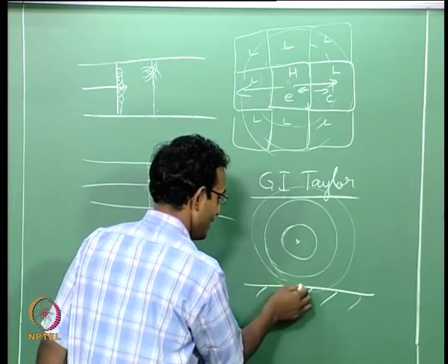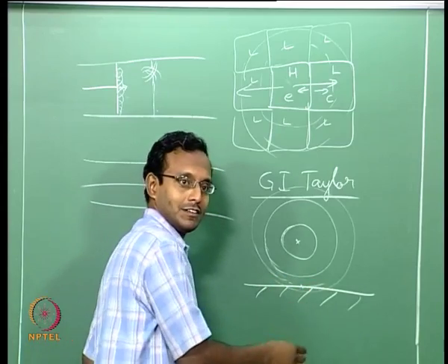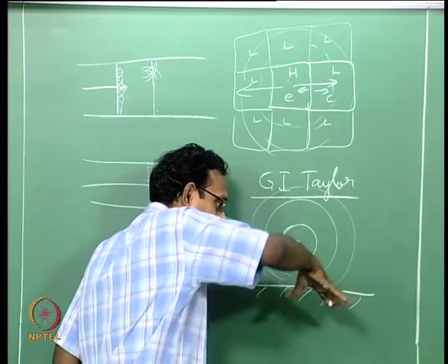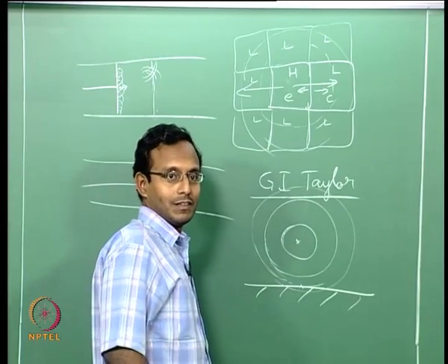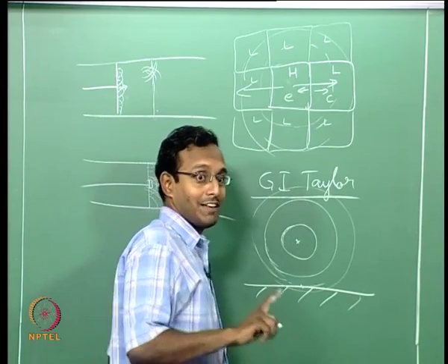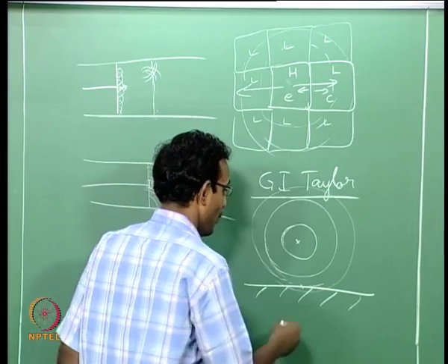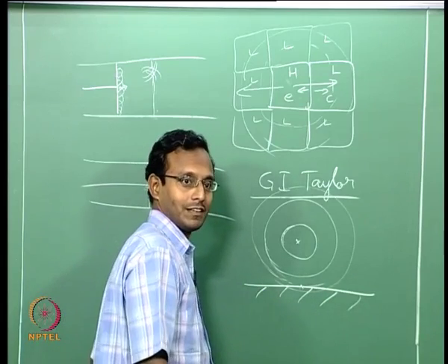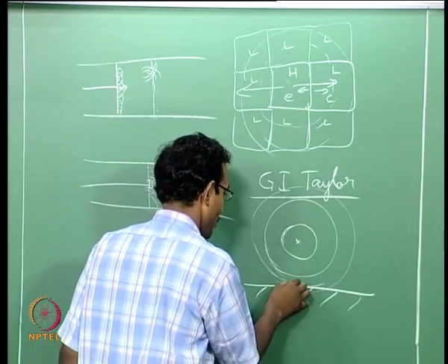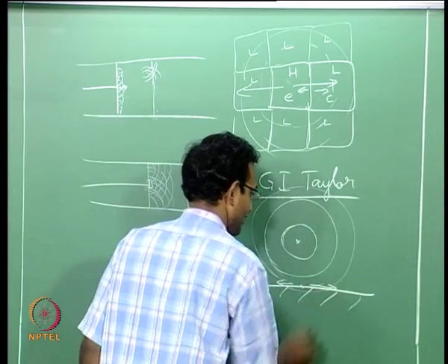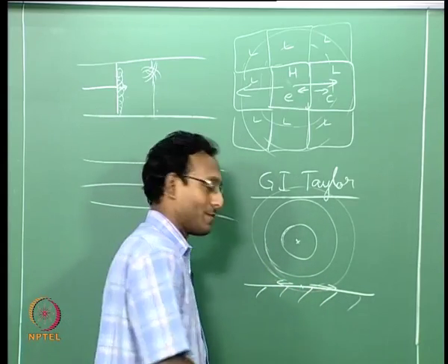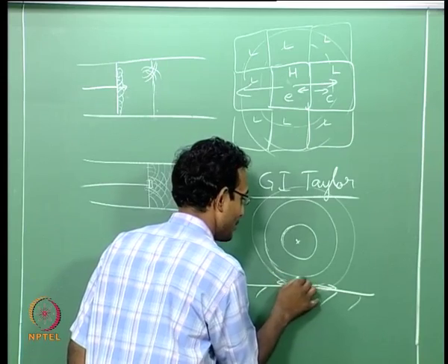It will just see a shock coming and touching it, and then a shock going on the surface outward. If that is the case, then I will never have flow coming inward. Okay. It will just be a flow going outward like this, it will never be flow coming back inward. In fact, this shock will bounce back like this.